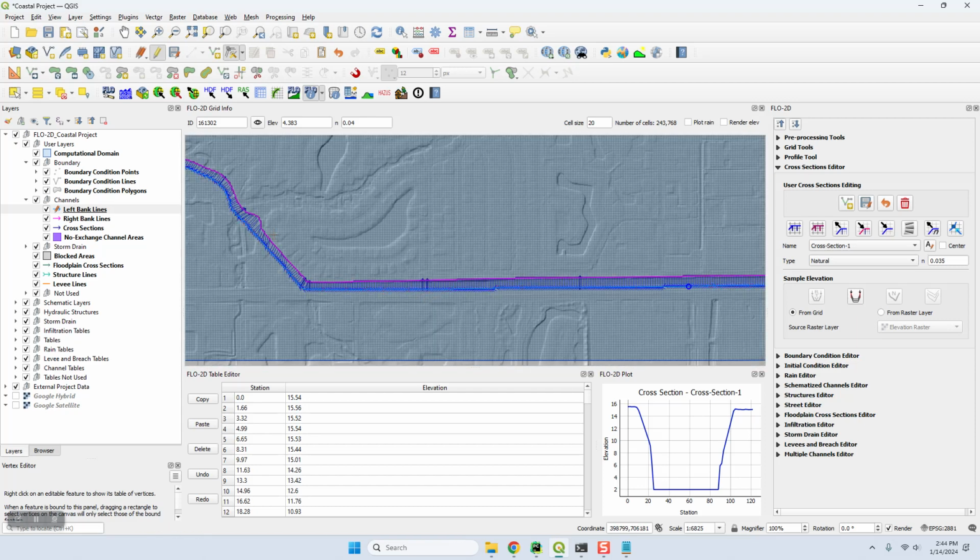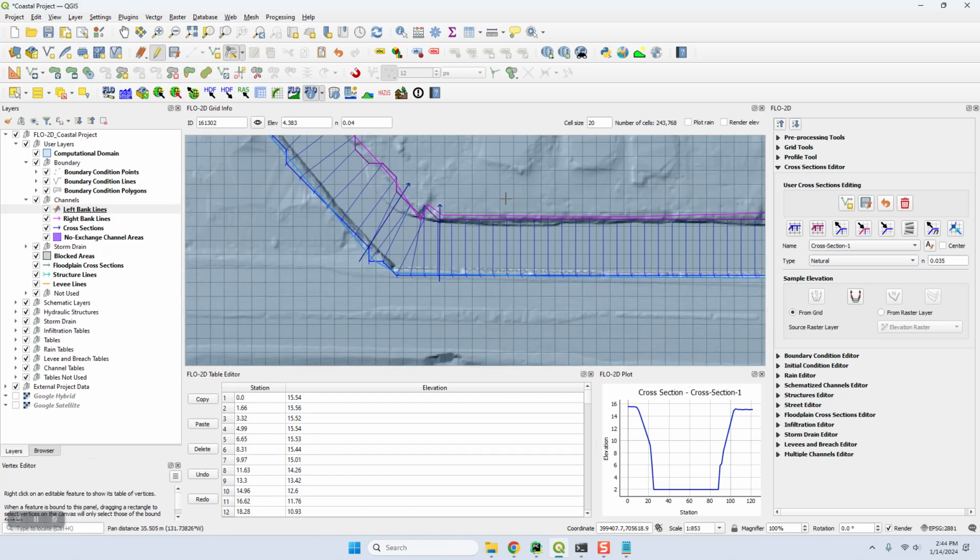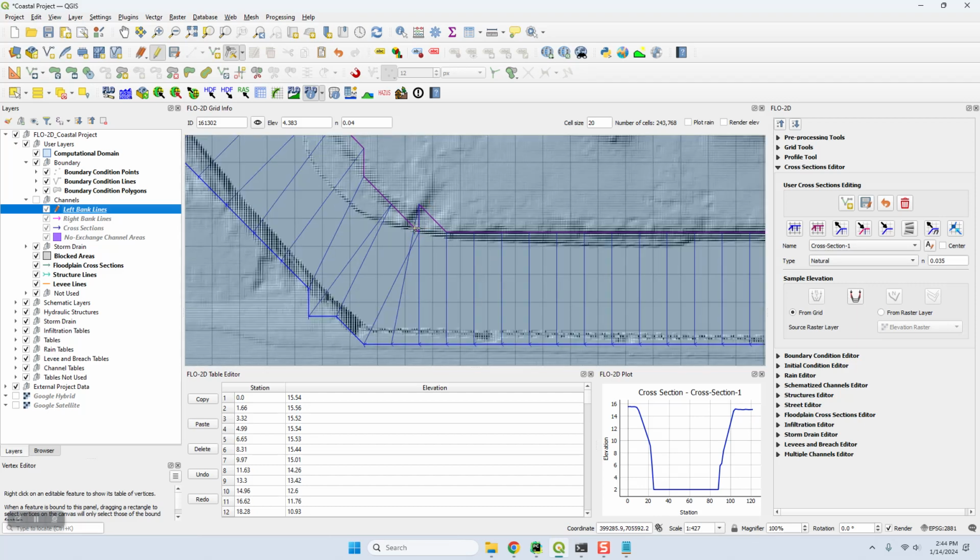I also did another one over here on a right bank because I wanted you to see one more issue. Now this time I'm going to turn these off because I want you to see what is happening here. What is happening here is that we have a right bank assigned to the interior of a channel. But when Flow2D runs, these interior grid elements are removed from the simulation and they're replaced by the 1D channel. So assigning a grid element to an interior node causes an error.